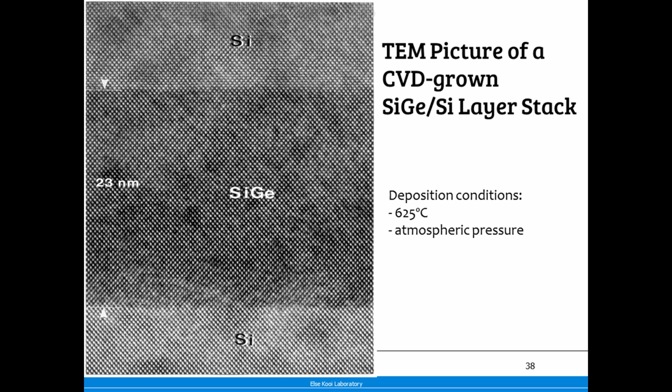Here is the first attempt to grow silicon germanium in an Epsilon reactor at atmospheric pressure in those days. Absolutely perfect. Well, not just from the high resolution TEM, because it shows you only a very small section of the crystal. You see how sharp the transitions are. The dark coloration, by the way, is caused by the strain. Substrate, silicon germanium layer, silicon capping layer.